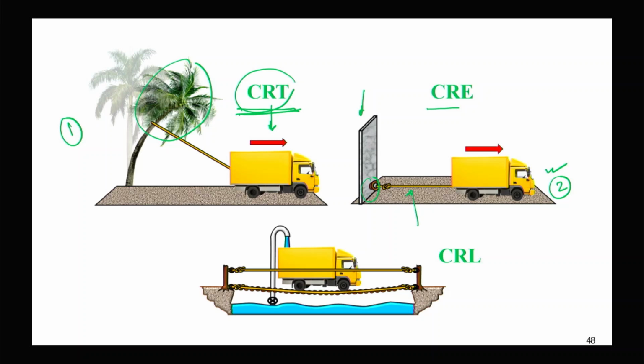And as the truck is being filled by water at a constant rate, the loading is at a constant rate. So it's called constant rate of loading. We will find different situations in practical applications where constant rate of elongation, constant rate of loading or constant rate of traverse takes place. Due to these, the stress strain behavior changes.